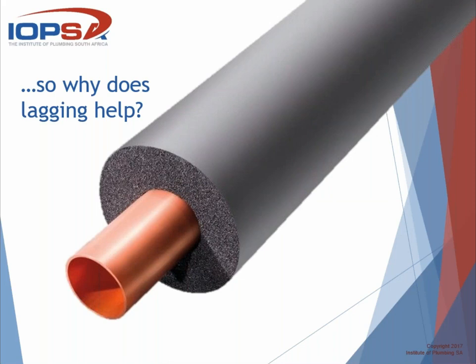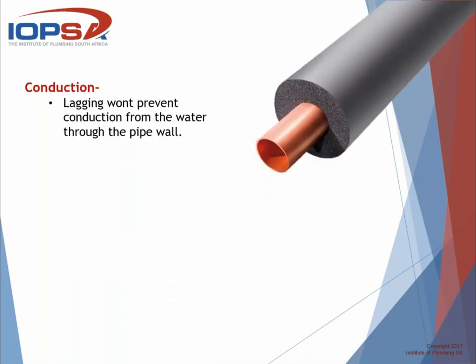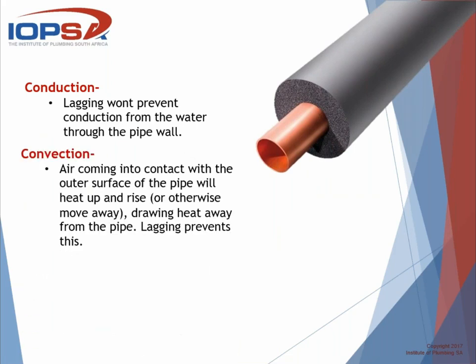Okay, so how does lagging help this? Well, let's have a look at conduction. Lagging won't prevent the conduction from the water through the pipe wall. Your outer surface of the pipe wall will still get just as hot as it was without the lagging. However, when we look at convection, now it starts to help, because what did we say?